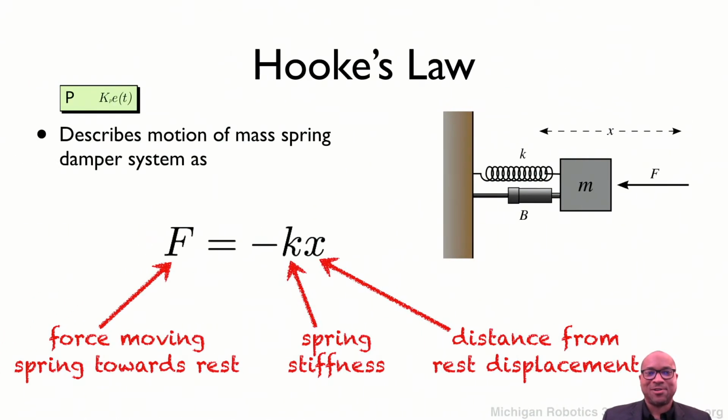But coming back to Hooke's law, what it represents in terms of PID control is that the control force that's going to be output is proportional to our displacement from rest, or really the displacement as an expression of error, multiplied by some spring stiffness. That spring stiffness is something we're going to have to determine, and it is its contribution to the control force of the servo.